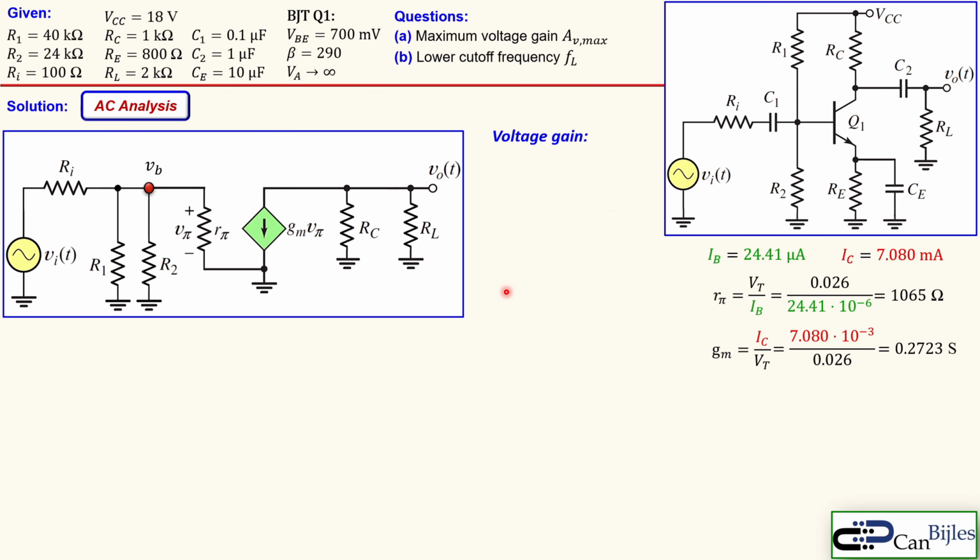So that is the voltage gain we are looking for. And that can also be separated in two parts, which is actually VB over VI. That's actually this part first. And then going from here to the output, which is V over VB. You see actually the VB can then be divided out and you get exactly V over VI back. So this is more convenient and easier to do instead of directly V over VI.